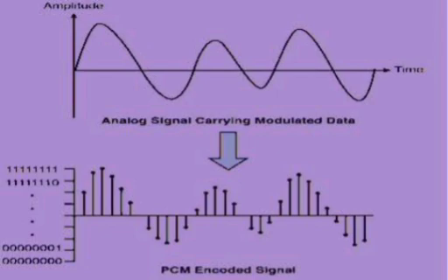Channel coding. What are the channel coding techniques? Hamming coding, convolution coding. Source coding is done for data compression in order to transmit it more efficiently. Channel coding is done to reduce the probability of error. Efficiency of encoding techniques: efficiency is given by eta equals H by L bar, where H is entropy and L bar is the average number of bits per symbol according to the encoding technique.